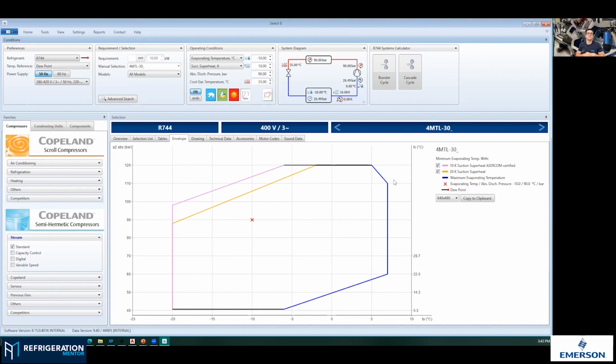and have this compressor trip. And some of the protections for this, so we're talking about the maximum evaporating temperature and that high mass flow. So on the CO2 system, I'm pretty sure what I see is maximum MOP, so maximum operating pressure settings in the case controllers a lot of the times, in those evaporator case controllers. So it'll limit those electronic valves opening up. And the way they used to do it in the old HFC systems, they would have maybe a CPR or a pressure limiting TXV. Is that correct? Yeah, it's correct.